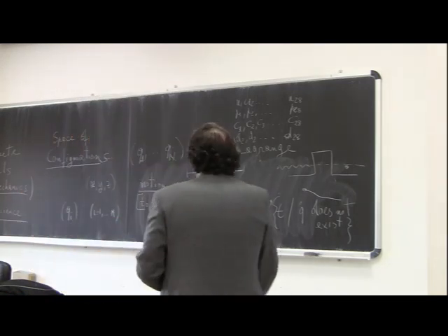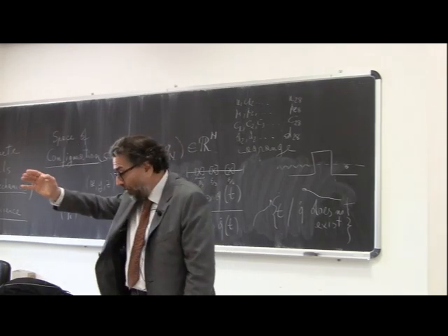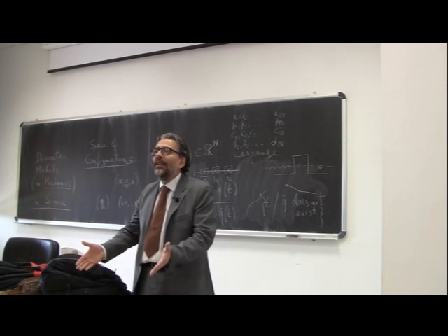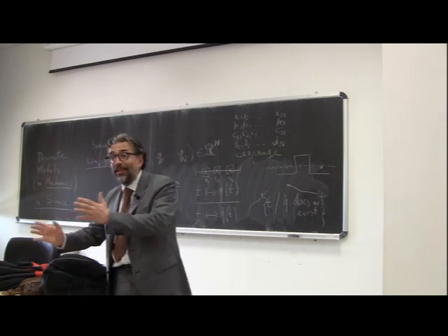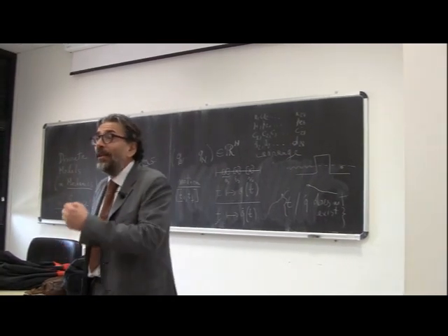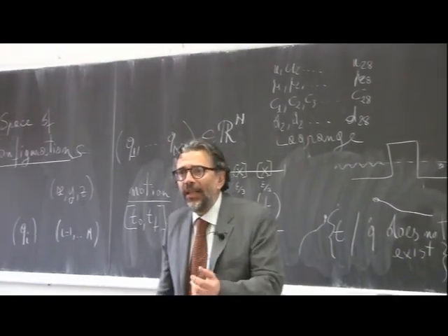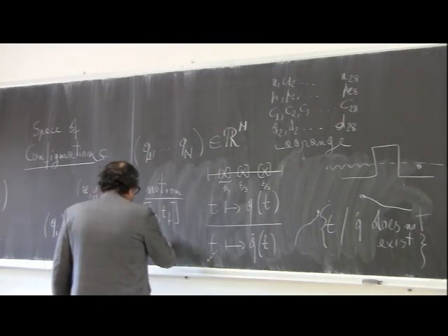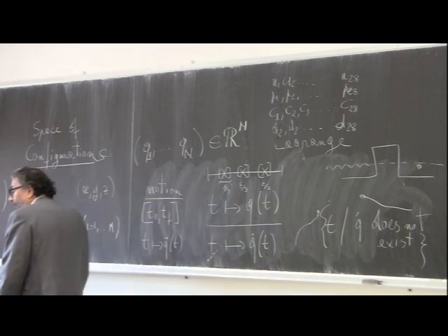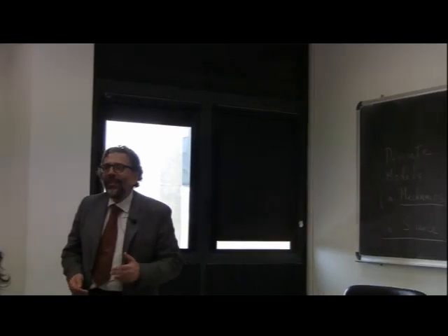Why do we need some discontinuity of q dot? Because of impulse. Look, I have this. It falls. When it touches, its velocity becomes suddenly 0. So the derivative cannot be continuous, and it doesn't exist on one side and the other side. So if you want to include impulsive mechanics in your scheme, then you have to assume that q dot doesn't exist in a few points. Similarly, you assume that you have the second derivative with respect to time. Okay? So the motion is a continuous function which has very often, you allow me this, the first and the second derivative. Okay? This is a motion.